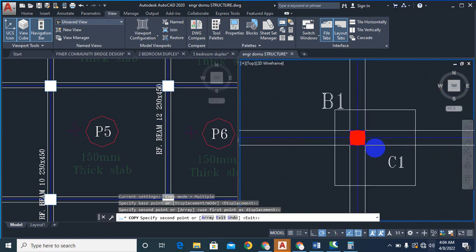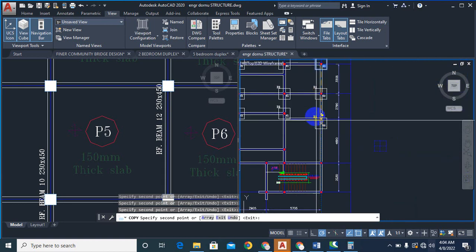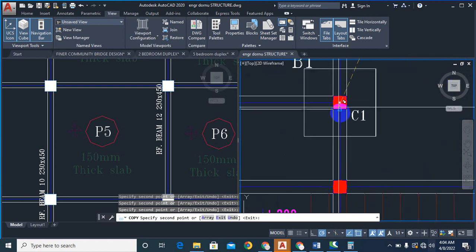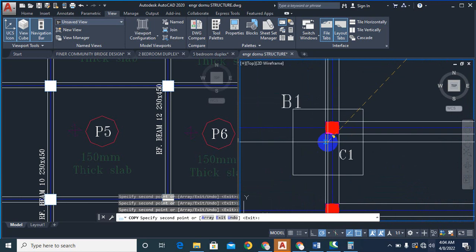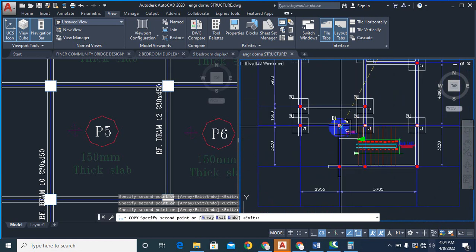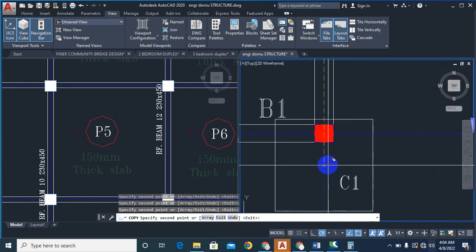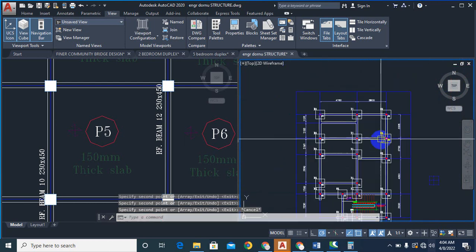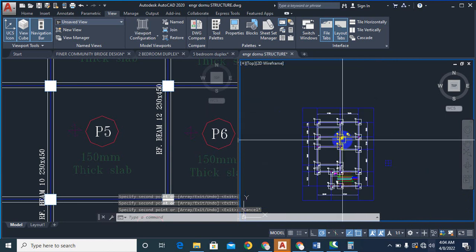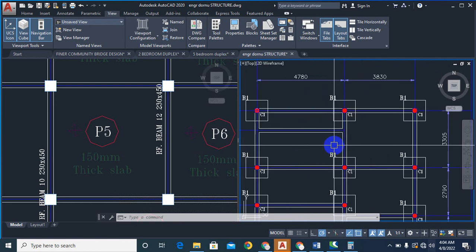So you are getting all this from your design. So mind you, please, this is not a design, this is just detailing. I'm not designing right now. I'm detailing. I'm trying to come up with a general arrangement. Okay, so this is actually the main general arrangement. General arrangement means structural layout. You are positioning where your columns and your beams should be. So I'm just trying to position them.